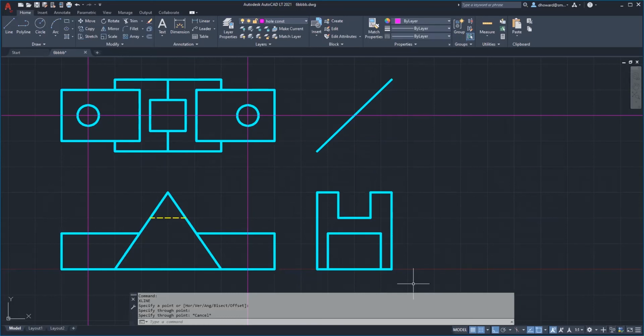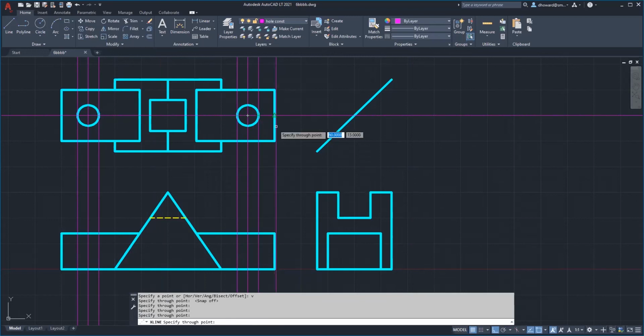So now I've got the basic center line construction lines for these holes, and that's always your first step. That gives you something to click on to do the other ones. So let's do the other ones. That would be the sides of the holes. So we're going to type XL enter, and I'm going to go V for vertical, and I'm going to click on these points here. And again, you should have just your object snap on for this so that you're for sure getting these intersection points and not some random point on the grid.